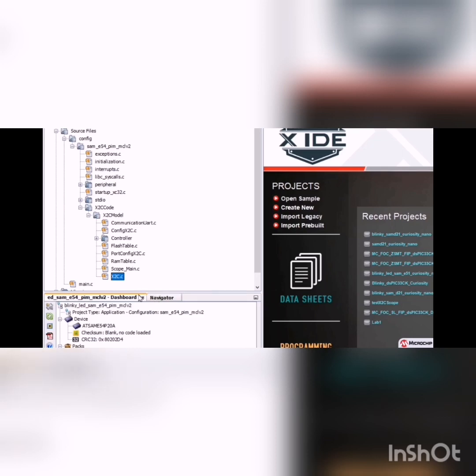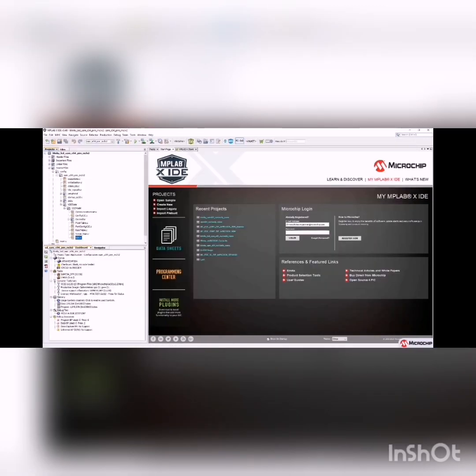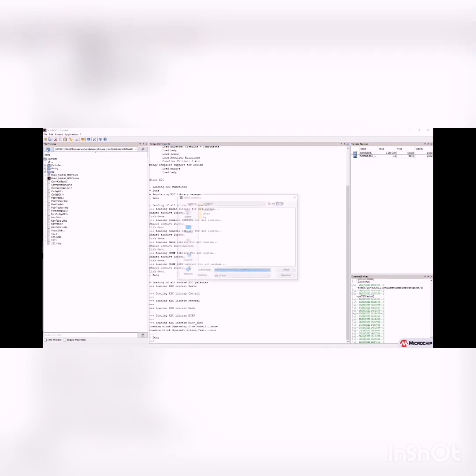So you click on the x2c.c and you open the file location with the Windows browser. You copy the path and you open Scilab. Once Scilab is completely loaded, you go to the file browser and you copy your path. You will end up in the location where you will also find the corresponding ZCOS file. This is the model file for your project. You double click on it and the model opens.